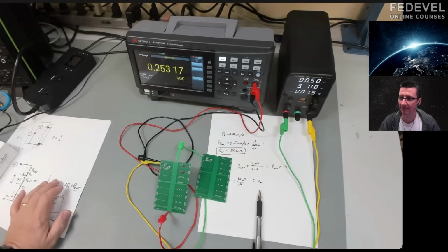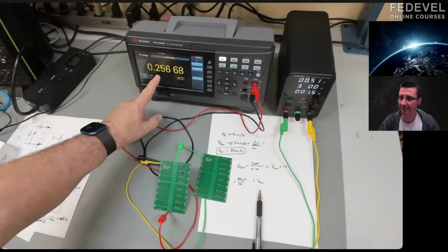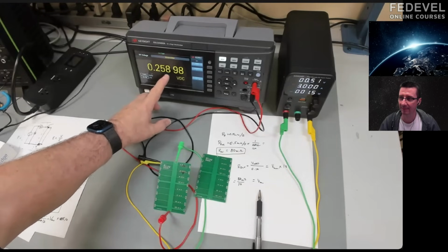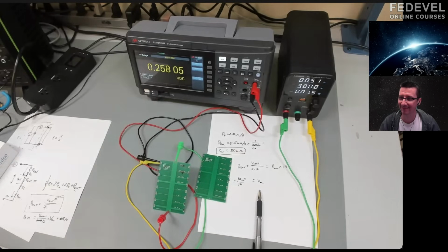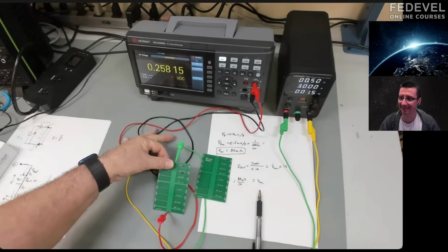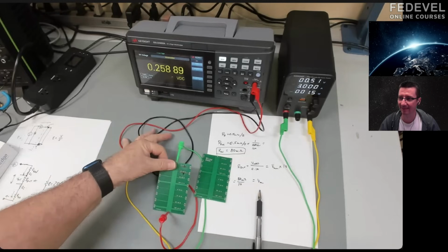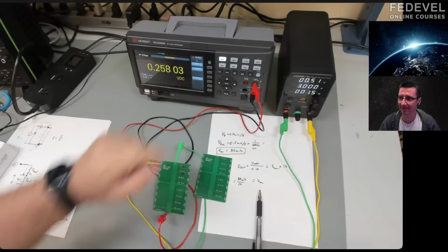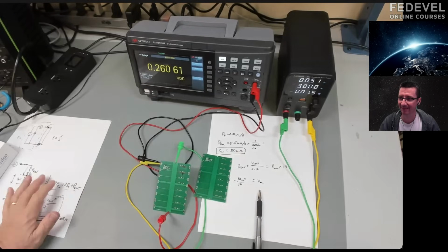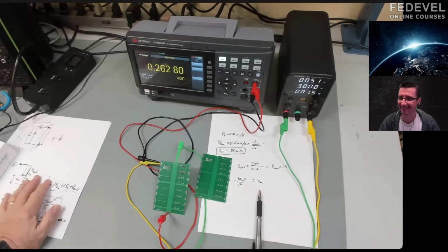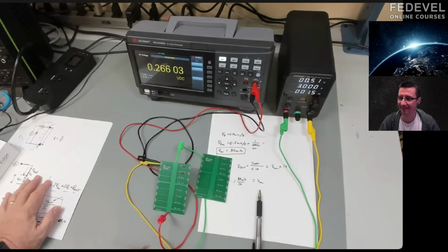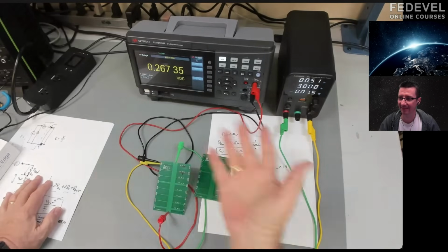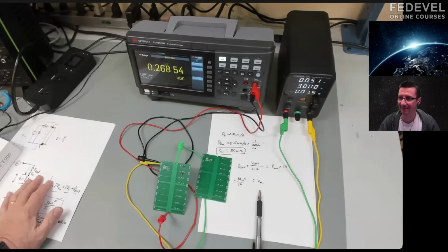Three amps. Okay, now at 3 amps, it's 256, 257, 258. Oh my gosh, it's going up. 260, and ow, that's hot. So at 3 amps, it's noticeably hot. When I touch it, I cool it, I suck the heat off, it drops way down, and now it's self-heating and going up. It'll reach an equilibrium as the power consumed in the wire matches the power dissipated into the air. But it's going to get warmer.